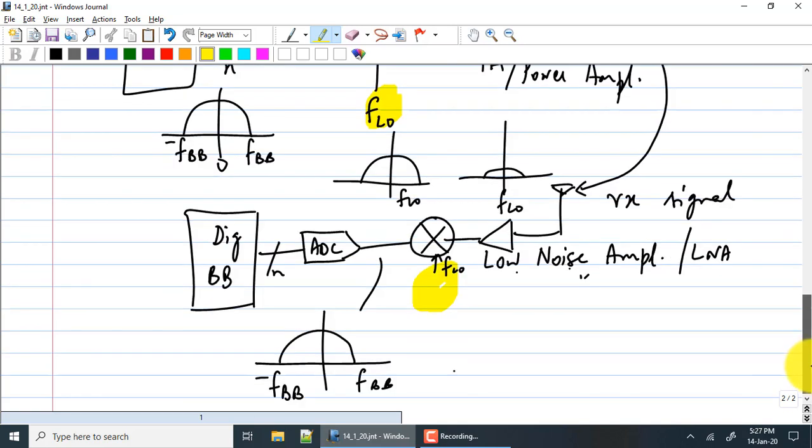So broadly, we have come up with a very simple block diagram of the transceiver. Pretty much every transceiver which you see will have a transmitter and a receiver, and probably a synthesizer. The transmitter will have power amplifiers and upconversion mixers and some other associated circuitry, which we'll work out the details of later.